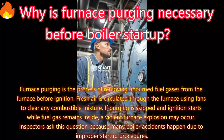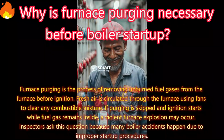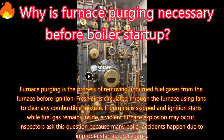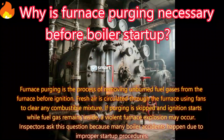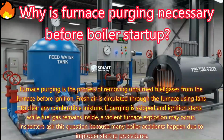Answer. Furnace purging is the process of removing unburned fuel gases from the furnace before ignition. Fresh air is circulated through the furnace using fans to clear any combustible mixture. If purging is skipped and ignition starts while fuel gas remains inside, a violent furnace explosion may occur. Inspectors ask this question because many boiler accidents happen due to improper startup procedures.